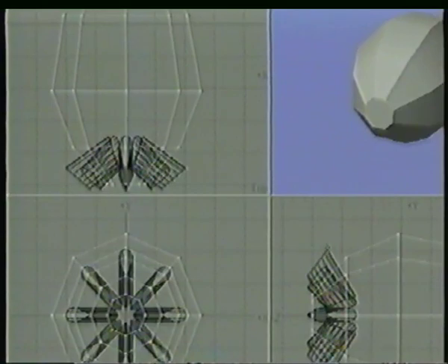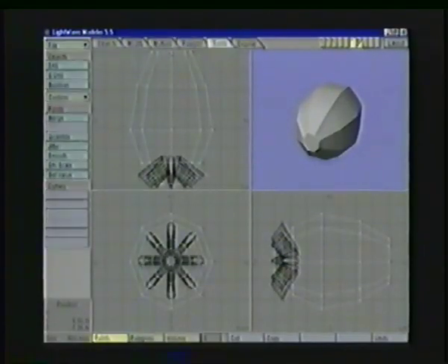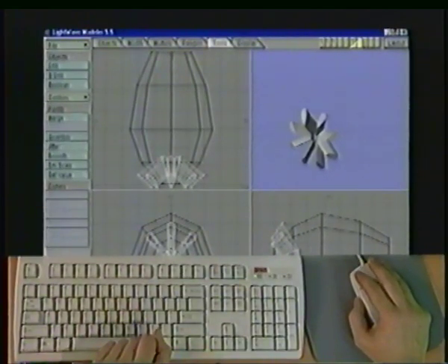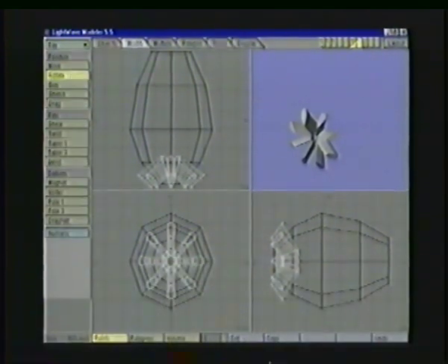I'm going to cancel this because there's one other thing I almost forgot to do, and that is to rotate these into position. So once again, I'm going to hit the apostrophe key to swap my front and back layer. I'm going to go to Modify, Rotate, or Y on the keyboard. I'll place my cursor directly in the center, and I can check to make sure it's the center by making sure it's at 4.5 and 0 on the x-axis.